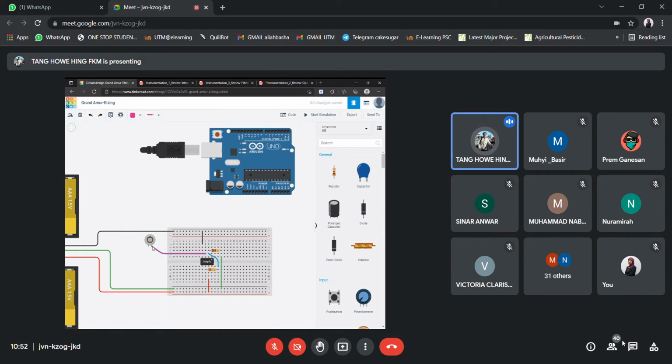Okay, so the anode voltage enters into the non-inverting input and is amplified by this non-inverting amplifier, and therefore the output over here is pin number 6. That is the output, and it will go to A0. Okay, so I think I'll just do something like this. Okay, so it is connected to A0.